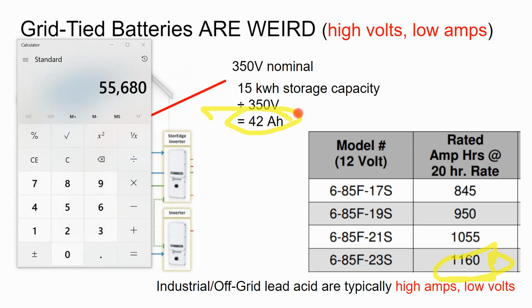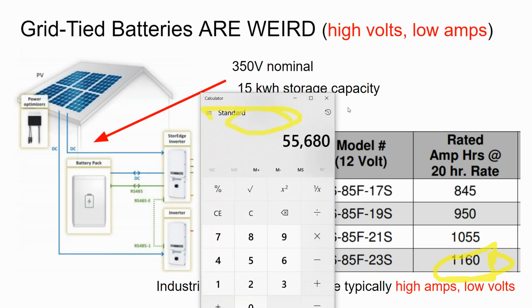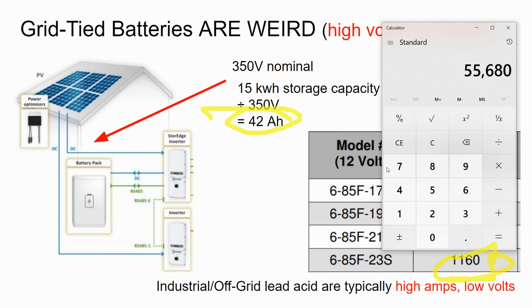And so they limit them to these 2 kilowatt or 3 kilowatt critical load panel infrastructure. If you wired it up to a central air conditioning unit, the storage capacity would be so small for their kind of entry-level products that it would just zap all the power out of the battery bank. And so that can kind of trip you up a little bit cost-wise, given that you're not just buying the lithium-ion battery, you're buying all the hardware that you need to get the lithium-ion battery to work.